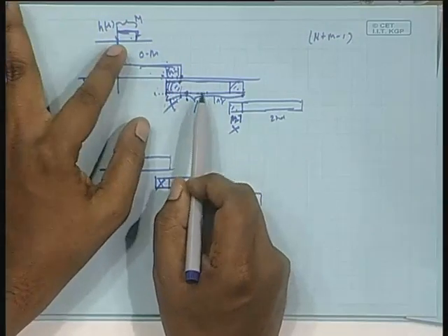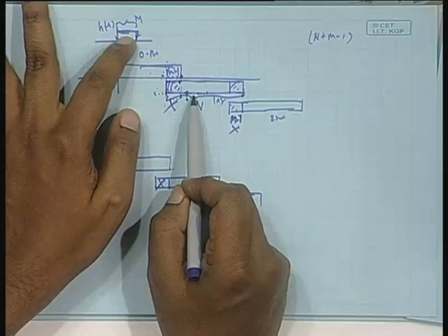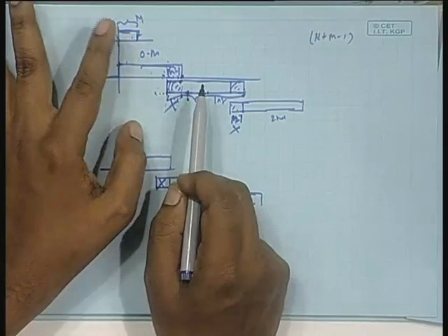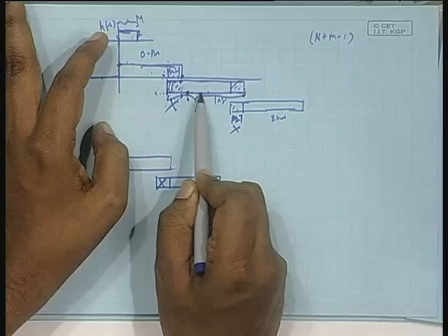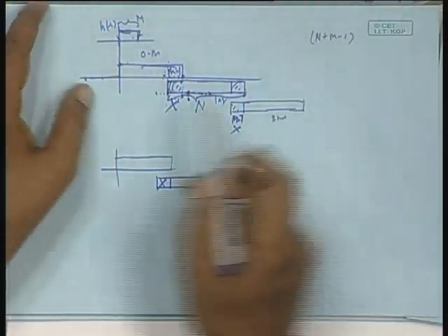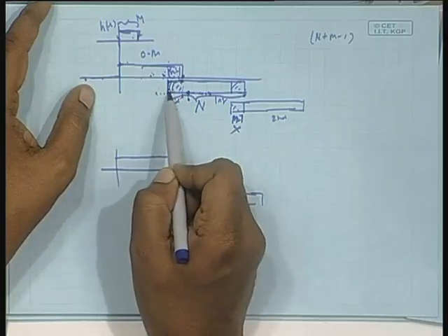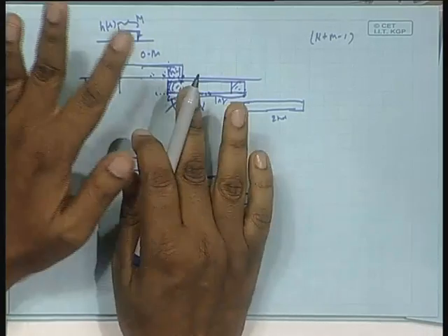Afterwards, you get the real linear convolution output between this and this, and I am interested in that linear convolution, because at this point, at this point, at this point, when I convolve, even when the data is contiguous, there is no contribution from this tail. This much is enough. Are you following me?